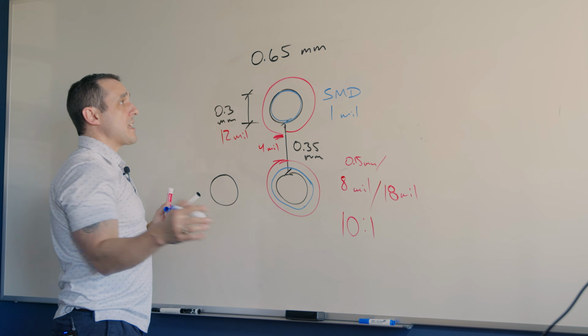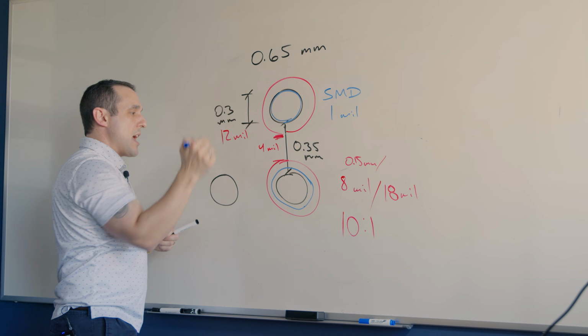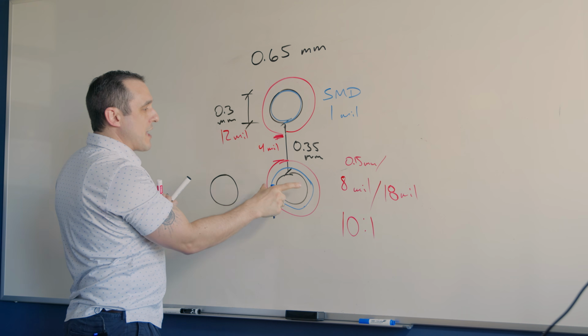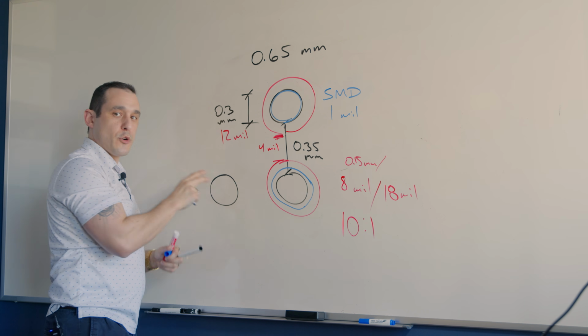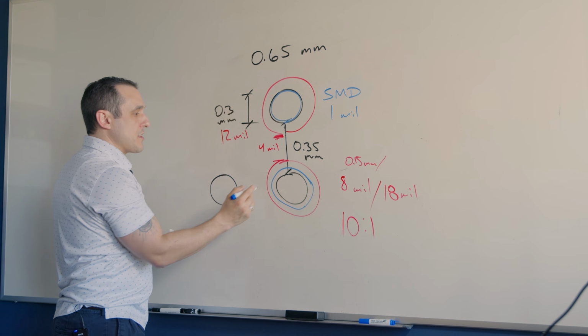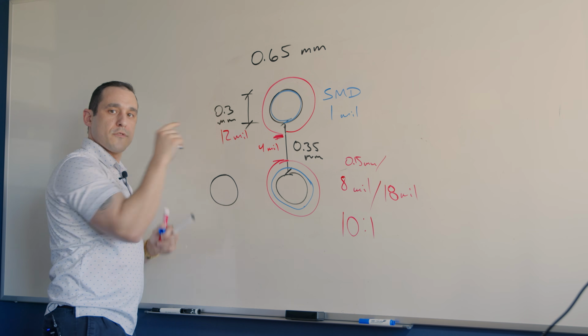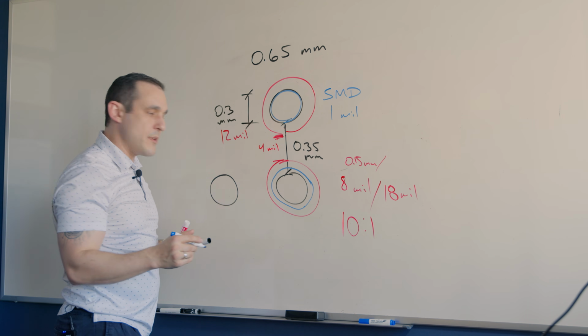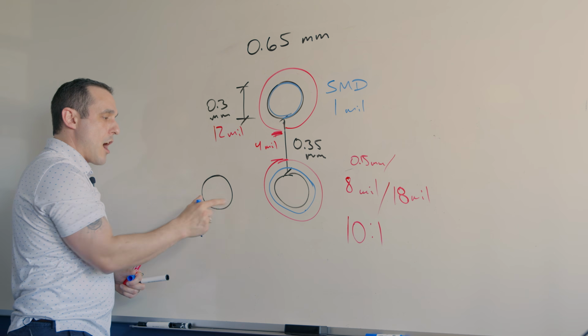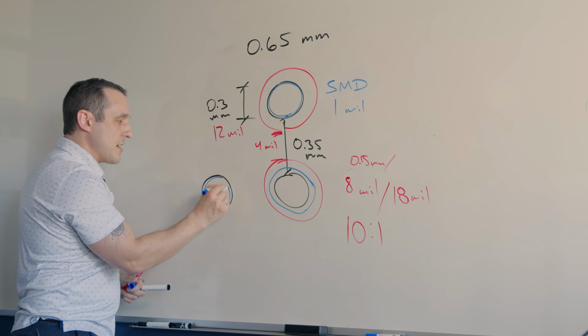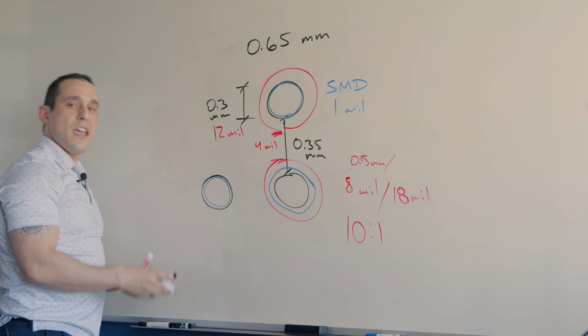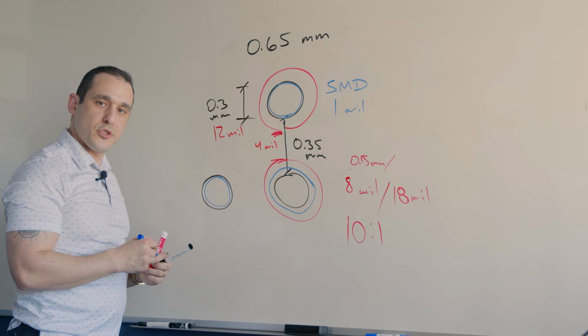So the solution in this case, where you have a finer pitch BGA and you have some of your pads with via in pad, but some pads don't have any vias in them, you want to set the solder mask opening equal to the amount of copper that needs to be exposed for soldering this BGA onto the PCB. To do that, you can oversize this copper just a little bit and then apply a small negative mask expansion in order to account for solder mask misregistration tolerance.